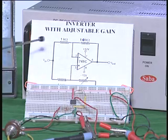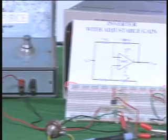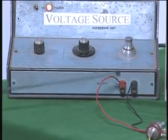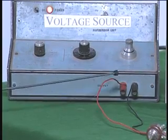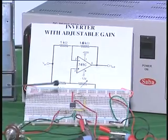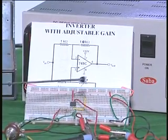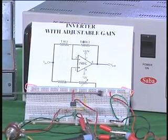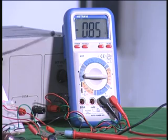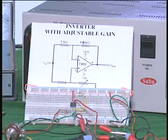So, here the input is again from a voltage source, and the output, I have not changed the output, it is again about nearly 1 volt. So, that is connected at the input of the circuit, and now I am measuring the output of the circuit by connecting the multimeter, and if you observe the multimeter, it shows 0.85 with the potentiometer in 0 position. You can see the potentiometer I have got here connected.